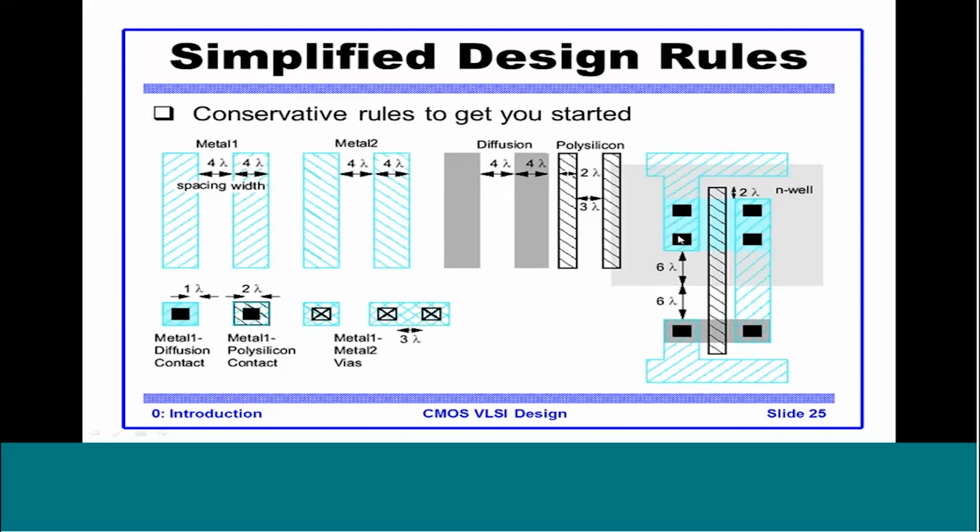The contacts here are source and drain contacts. So both the drains are connected together. On the NMOS side, this is the source which is tied to ground. These are the diffusion regions. Again this drain is connected to the PMOS drain. Again, this is the diffusion region. The source of PMOS is connected to VDD here.